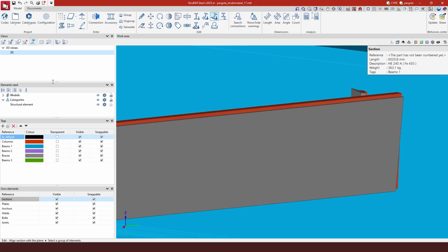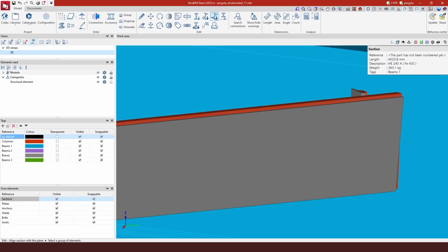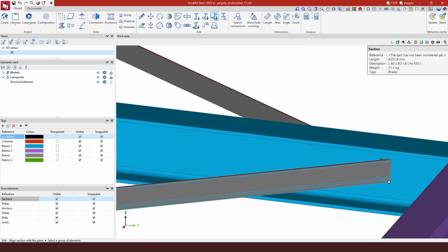The beam model is right now being red, and that's why its elements can be managed from the Elements red menu right here, where we can make them visible or not. You can tell that the red, meaning the beam model, had a little angle with the one that we have right now. It was only 3 degrees, so that's why it's hard to tell, but it had it.